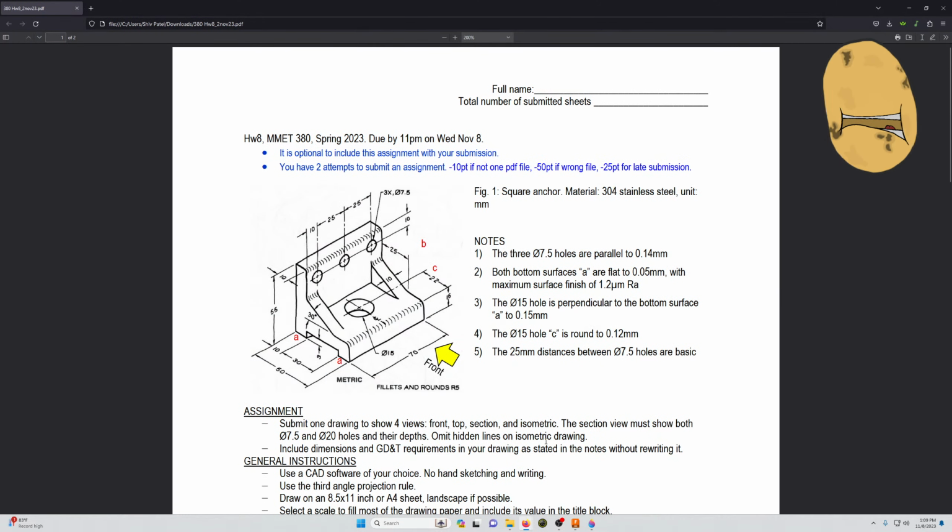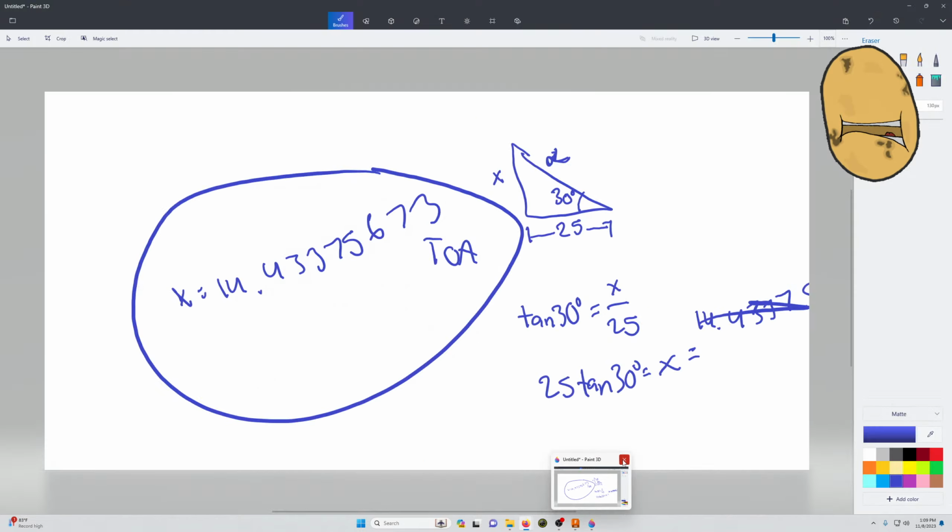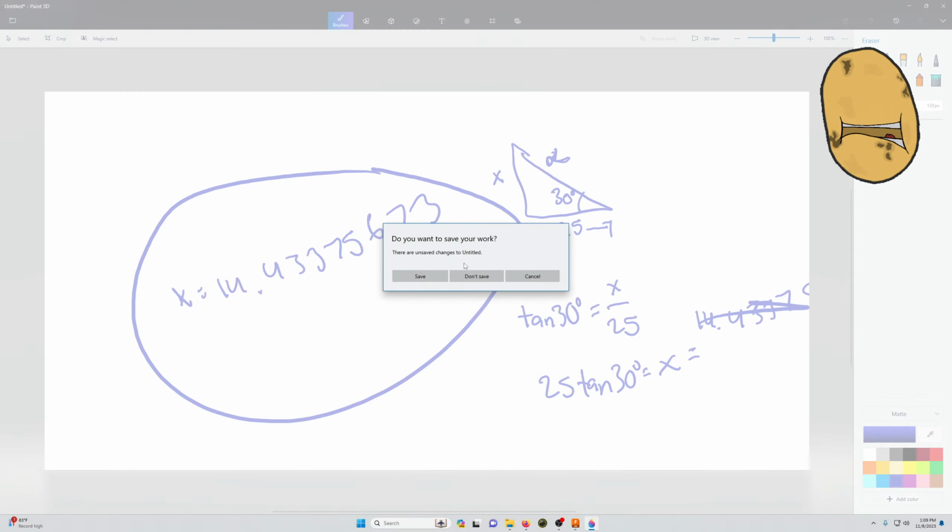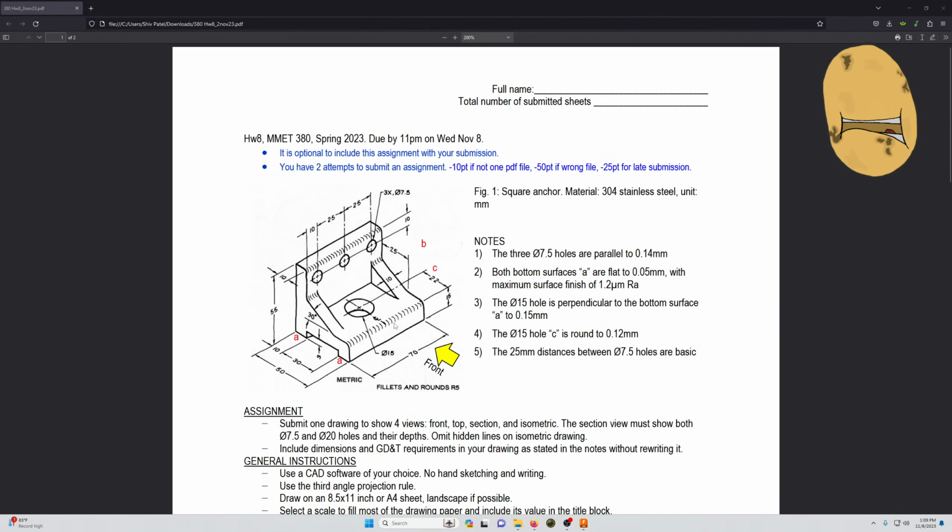So now we're gonna create our holes. So I'm gonna delete this guy because we probably don't even need him anymore. Don't save. We're gonna create a hole right in the middle. It is going to be 22 out. And how far in? It's probably gonna be right in the middle. It is because you see this little plus sign. That essentially is a center line.